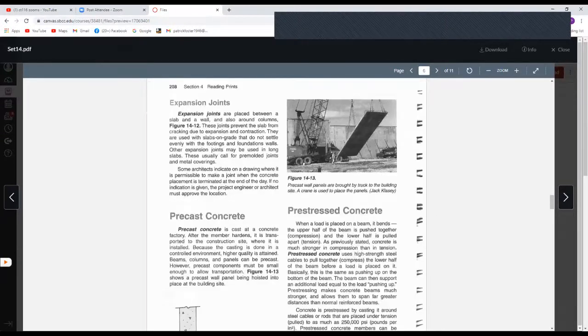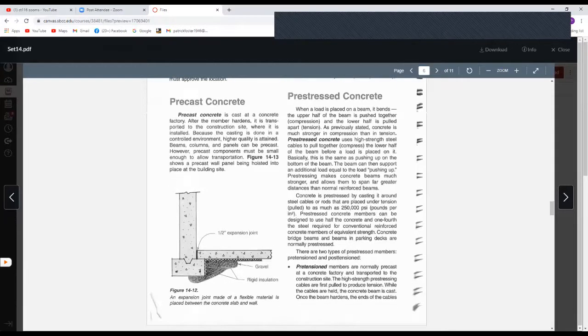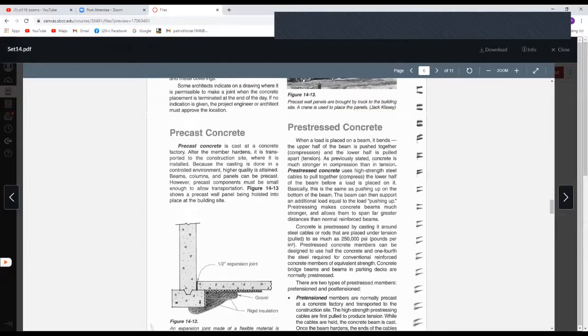And then expansion joints. This is something we don't have in homes very much. Although in cold climates, they do sometimes leave expansion joints even in a residence, because there's so much difference between maximum and minimum temperature that the concrete expands a lot more than in a place like Santa Barbara. Don't they sometimes insulate the slab?